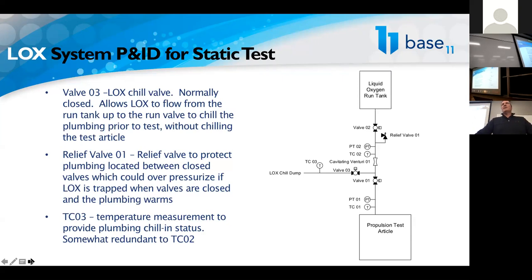It's the momentum of the fluid being slowed down that causes the water hammer. So in this case, with the system being fully wetted, when you open the run valve, the Venturi is limiting your flow rate right from the get-go because it's already wetted.